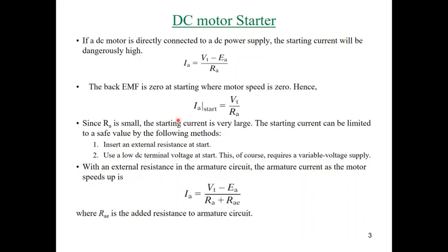So it's better to use voltage control instead of adding resistance. The other side is that if we add resistance to the rotor circuit, we have some extra losses in the beginning. This is not a big problem because the starting time is small, so we will not lose a lot of power. However, we still prefer decreasing the voltage using one device, because we can use it in speed control and braking as well.